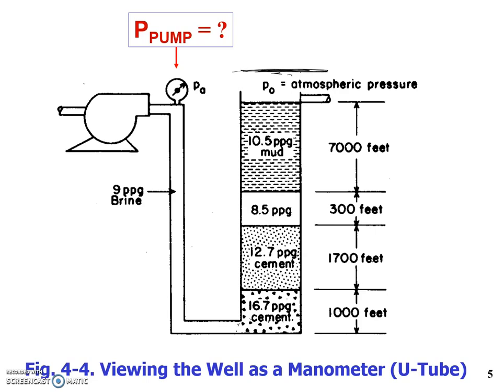And then we go up and the hydrostatic pressure drops until we reach this point. So you start from the right hand side of the manometer, you go down, hydrostatic pressure increases, you move to the left side, you start going up, the hydrostatic pressure drops. With what gradient? With this gradient, and here with this gradient it increases.